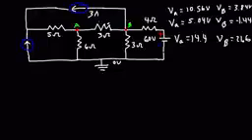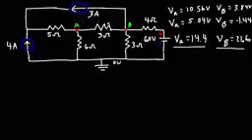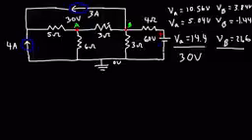So this was a 3 amp current source, and that was a 4 amp current source. Now what we're going to do is add the potentials at point A and point B. So the potential at point A is 10.56 plus 5.04 plus 14.4. So according to the superposition theorem, when putting all 3 power sources in a circuit, the potential at point A should be 30 volts. And at point B, it's going to be 3.84 minus 1.44 plus 21.6. And so the potential at point B is 24 volts.